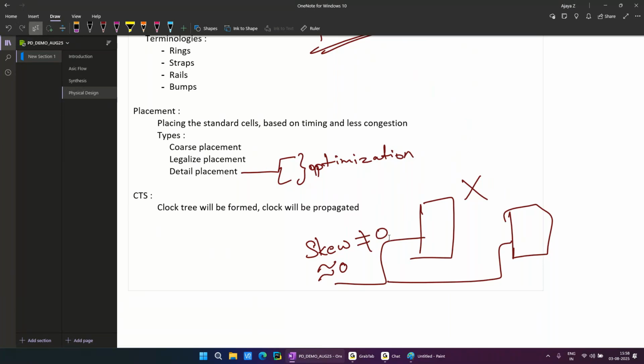Parallelly you will be hearing about crosstalk, EM, and all that with respect to the clock path also, how we can fix it, the rules specifying it, all that will be discussed. And from here there will be one more file called the spec file, the specification file. This is the major file in CTS, cts.spec. That is also one of the major interview questions. What does it contain? How can we modify it? How can we add more features? That is what we will be discussing.